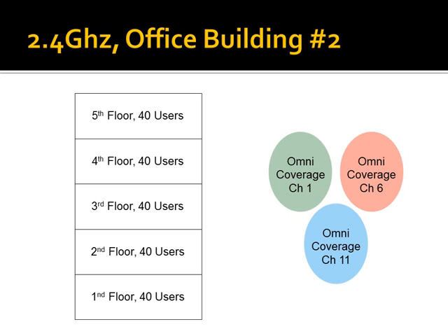Remember, these antennas are very narrow vertically. It's a way to do it. My point in walking you through all of these is you can't just think power. Power is important. Power is directly how we overcome path loss. It's not the only way. If we turn up the power, we start with more power, therefore the same path loss doesn't drop my receive signal as far. We're back to that path loss equation.